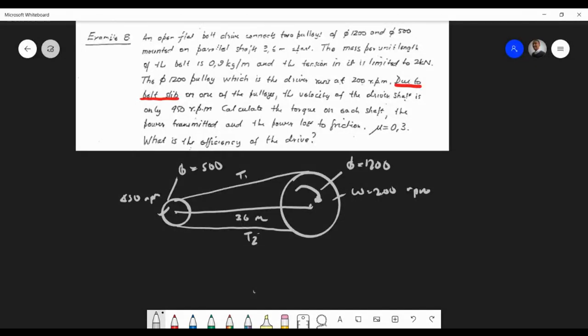Beautiful. We're getting close. So let's call this pulley 1 and 2. Normally V1 equals V2, right? Do you agree with that? But now you slip. V1 does not equal V2. So in essence, part of Matthew's answer was kind of right: you lose velocity. So remember students, when you see the words due to slip, you know what to do.